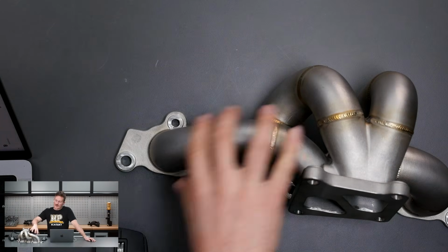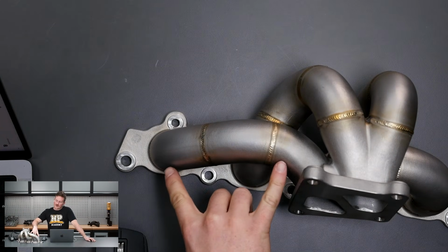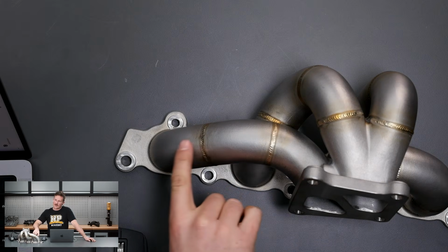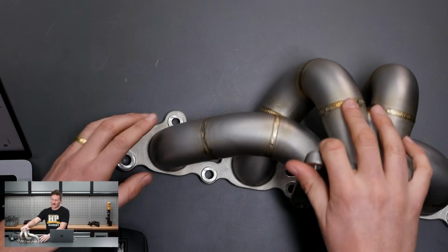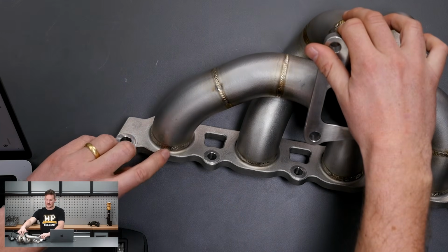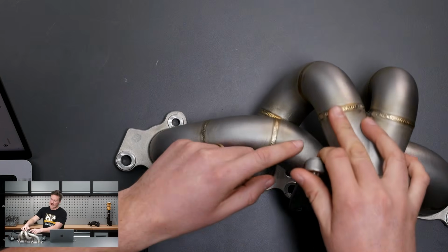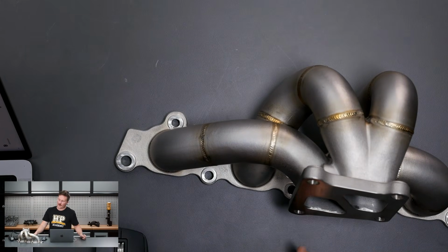What I will say is, I don't have that example open anymore. When I used it for doing this part here, you can basically pick up the centerline of this part and control how far along there the centerline goes. What I ended up doing was setting it so the centerline would only do the middle 70% of the part, so it would stop before it got down to the flange here and before it got into the turbo manifold here.